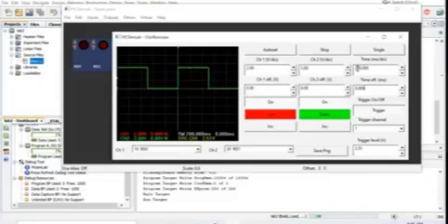Okay, the maximum value is 200 milliseconds. You can see from here, this is high, this is low. This is the trigger signal from channel 1. In the fine box, you can see here the grid represents 200 milliseconds. So we have 1, 2, 3, 4, and then the other one half, so 100, so 500 milliseconds. 500 milliseconds on, then 500 milliseconds off.